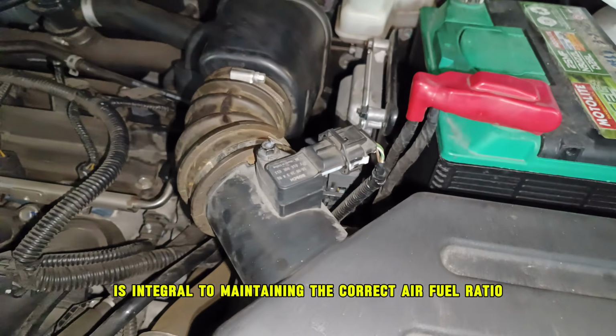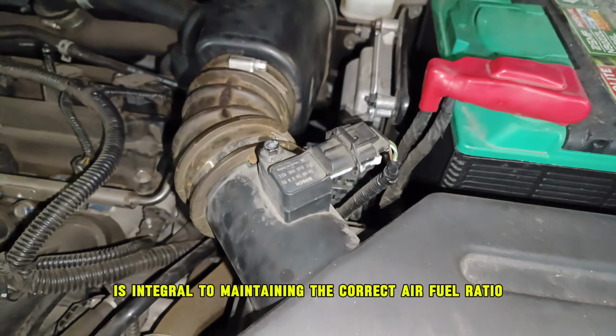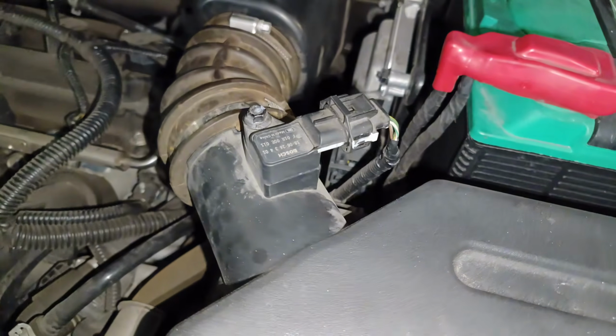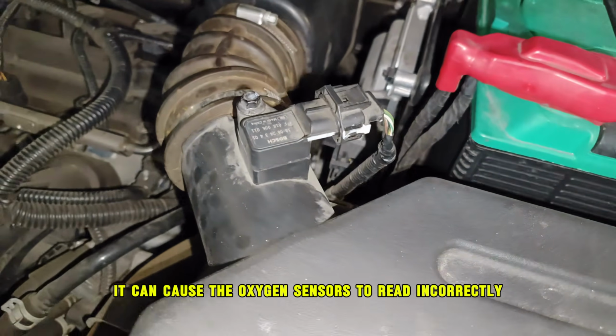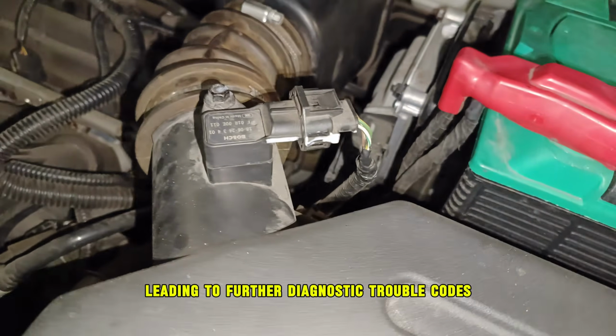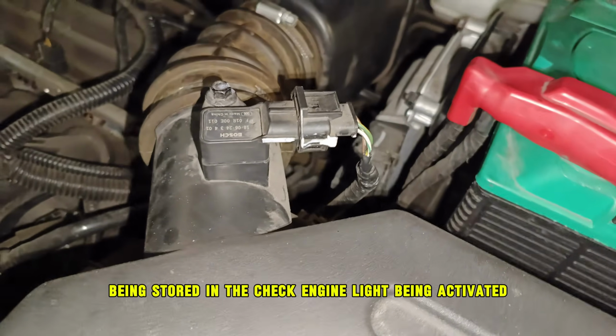Since the MAF sensor is integral to maintaining the correct air-fuel ratio, a problem with the sensor can affect other engine systems. For example, it can cause the oxygen sensors to read incorrectly, leading to further diagnostic trouble codes being stored and the check engine light being activated.